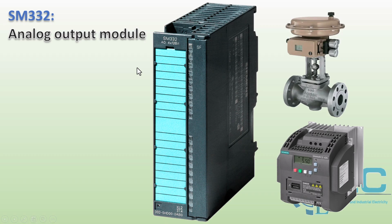Common applications include variable frequency drives, VFDs, to control motor speed dynamically, and valve positioners to regulate flow, pressure, or steam control. The SM332 module is available in several configurations based on the number of analog outputs: 2 outputs, 4 outputs, 8 outputs. The selection depends on the number of devices that need to be controlled and the specific automation system requirements.